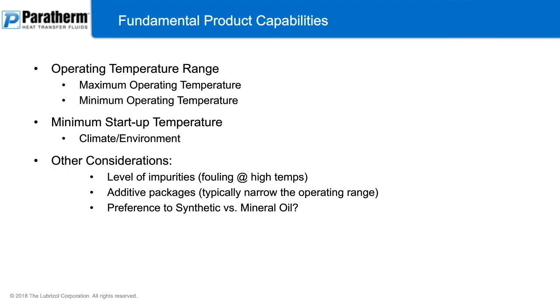Now, that's important from a physical standpoint, in that you need to get the fluid moving. What also becomes extremely important is that there's a lot of thermal stress during startup of a fluid. There's high heat being applied to a fluid that's not at its optimum viscosity to move through the pipes. So a fluid with a lower startup temperature is going to offer you much better fluid longevity and protection against premature degradation during the startup process.